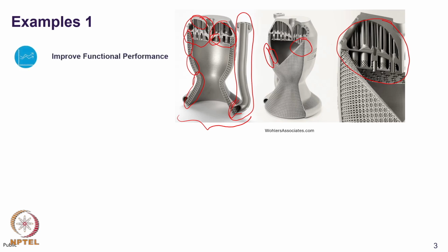Overall, additive manufacturing offers improved functional performance because we can create the geometries in various parts of the large structure as needed. For example, this fuel channel and the smaller channels in the other part of this large engine casing. We can have finer control when we are creating complicated geometries and lattice structures using additive manufacturing. So, it offers superior topology in complex geometry.